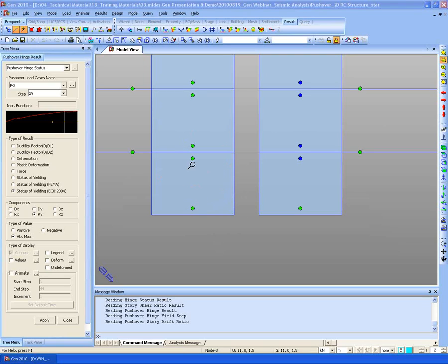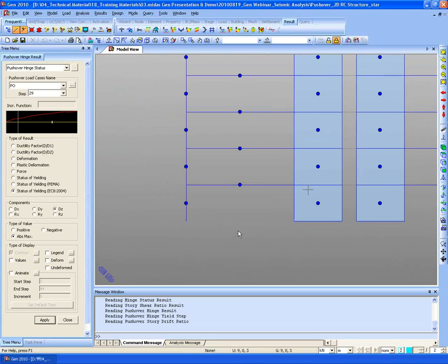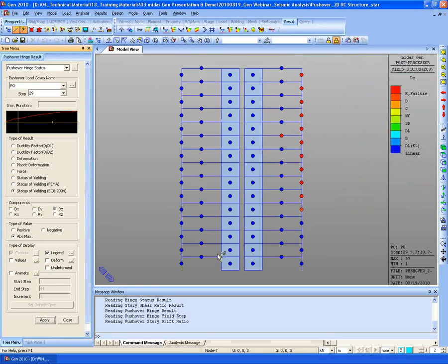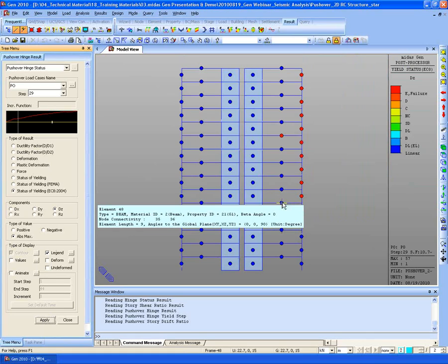So due to this property, we enter the hinge to I and j end for the moment hinge. But the shear hinge, I just mentioned, can be checked in the center of each element. So shear hinge is entered to the center.